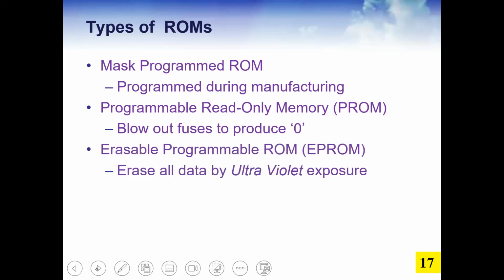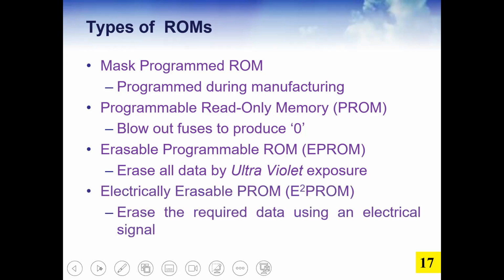The third category is the erasable programmable read-only memory, EPROM. It uses different techniques and it allows programmers to reprogram the same chip a limited number of times, let's say 10 times. It can be erased. And how will we erase the information? By exposing this chip to ultraviolet light. If we do this, the stored information will be removed, and then we can reprogram it. But again, a limited number of times, let's say 10 times.